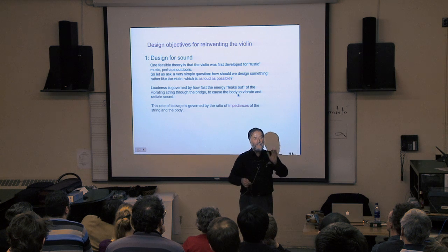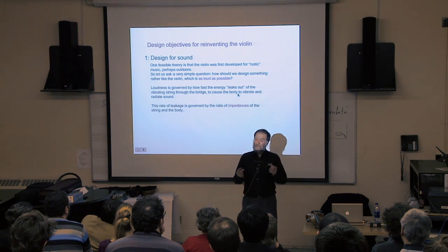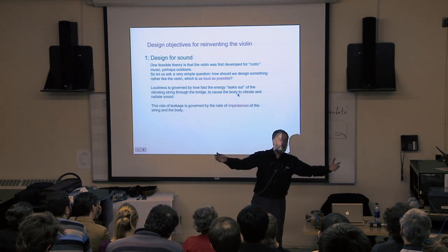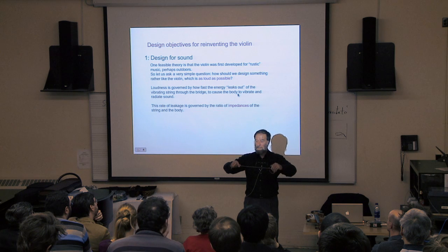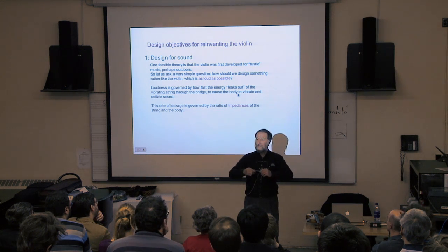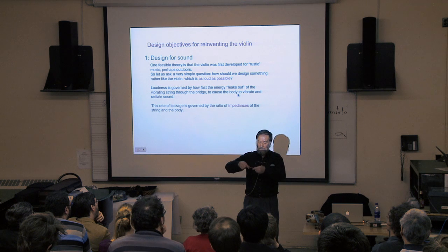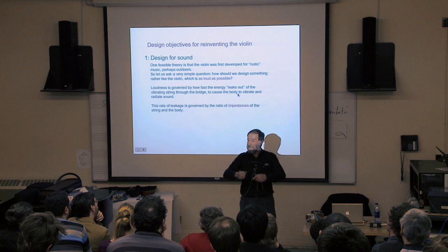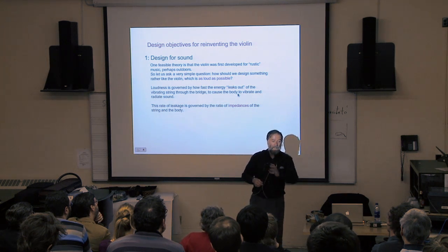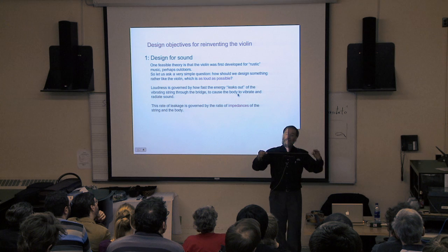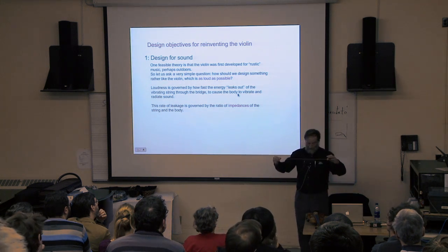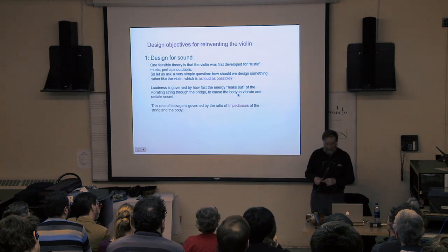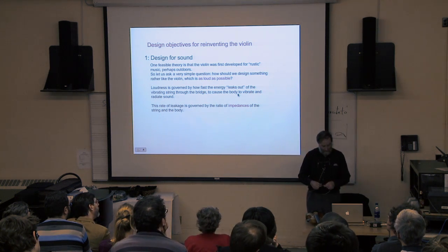If you want to make pressure waves in the air, you need a vibrating structure, but it's got to be a structure which is roughly as big as the wavelength of sound at the frequencies you're interested in. Here's a 1 millimeter string, vibrating at a few hundred hertz, wavelengths of sound this big, much, much bigger than the string, and the string vibrates through the air and the air just flows around it. The air has no reason at all to get compressed in front of the string and rarefied behind it, it just moves out of the way. So strings are good from the player's point of view at doing these tricks you want them to do. That's another story about exactly why strings are a good thing, but they're no good at making noise, so we need an amplifier of some kind, and all this woodwork here is a kind of mechanical amplifier.